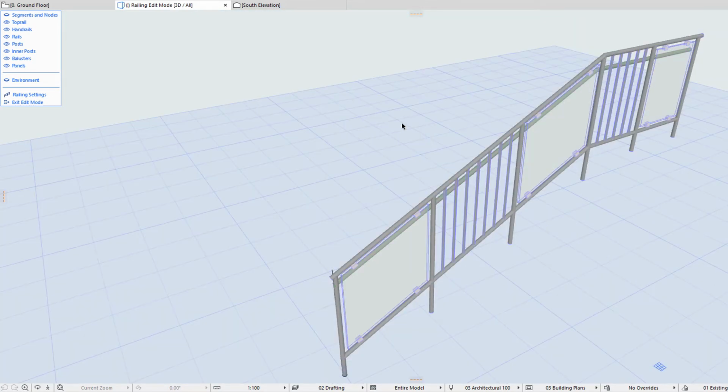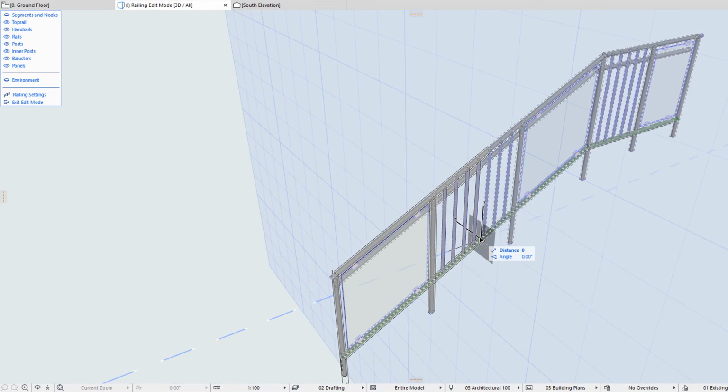If you select a rail, you can click any of its nodes or segments. The editing plane is displayed, and you can graphically edit its horizontal offset value with horizontal movements in the editing plane. This will offset all edges of the selected rail, or its rail height value with vertical movements in the editing plane, which will modify the vertical position of the rail.